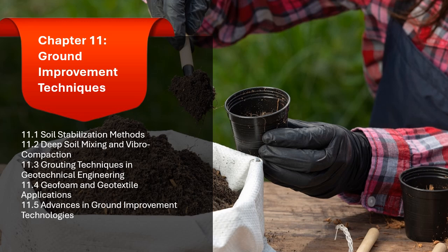Its use is particularly advantageous when traditional fill materials would result in excessive settlement or cause damage to existing structures. Example: in areas with soft soils or where ground improvement is difficult, geofoam is used in embankments or road construction to avoid differential settlement.